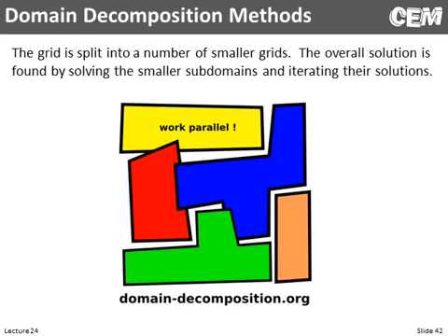There's another thing that's becoming very popular in finite element, and it's domain decomposition. What this allows us to do is we not only mesh an object, but we'll take one portion of that object, maybe send it to one CPU, take another, send it to another CPU, and they can do their number crunching and iterating back and forth in parallel. And so this really speeds things up. Rather than having one CPU looking at the entire problem, we have one CPU working at a little smaller part of the problem, a second CPU looking at another part of the problem, and so on.